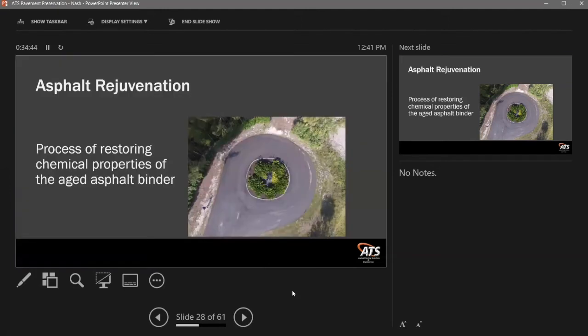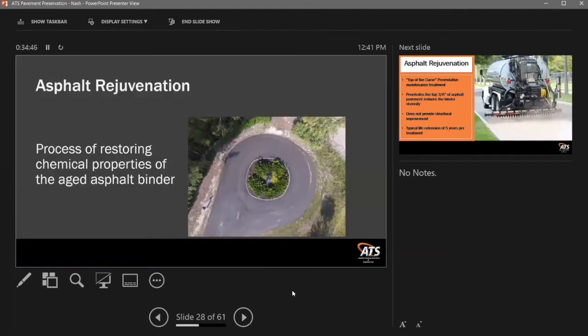So the next pavement treatment that we're going to talk about is something still superficial. So you're talking very, very on top of that curve. We're looking at a pavement surface preservation technique that is sometimes applied as early as 1 year after construction, and then consequently applied every 3 to 5 years afterwards.